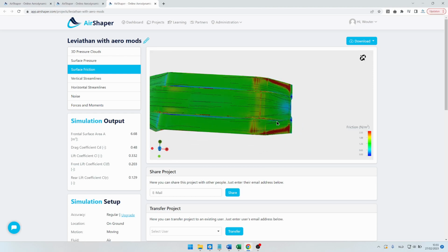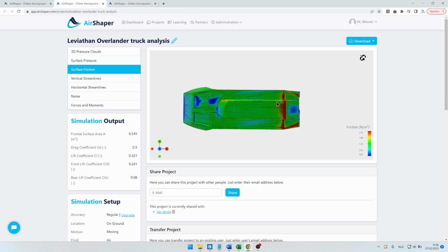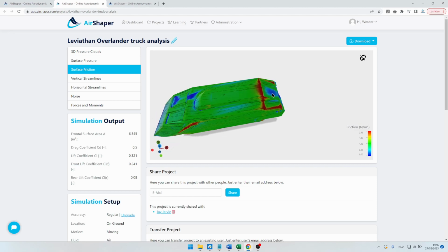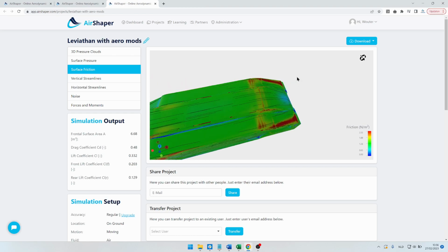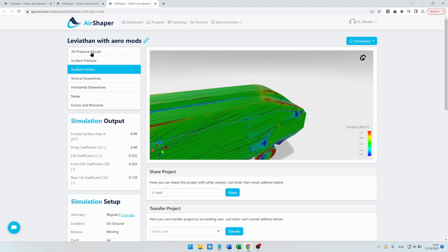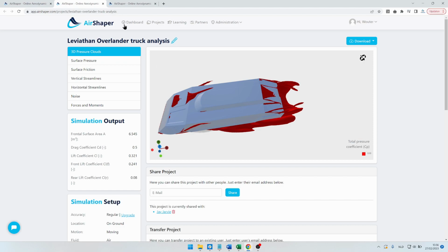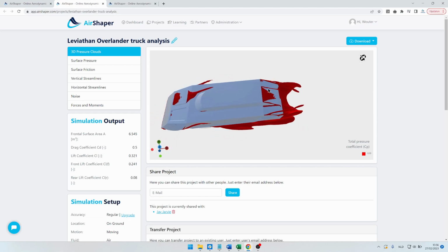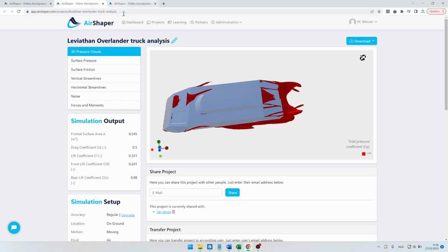They still curve inward because of the air joining from the sides, but compared to the previous one, you could see that we had flow going in different directions, also outward, and we had this blue patch here, which indicated flow separation, which we don't really have, or to a much lesser extent, on this design. And you can actually see this replicated in these, let's say, pressure clouds, is what we call them. So the original one had vortices around the side edges, and this one a separation bubble, not too big, it wasn't too dramatic, but still it was there around the central area. And this one features a much cleaner airflow around this central tunnel.